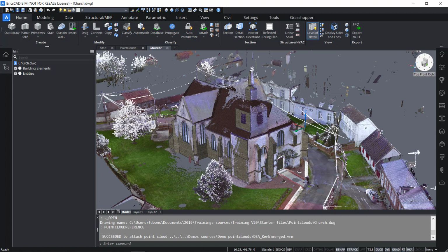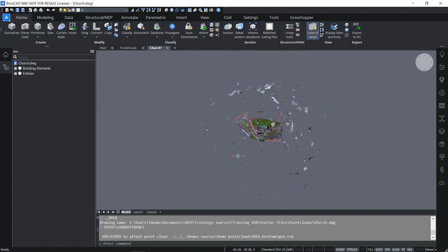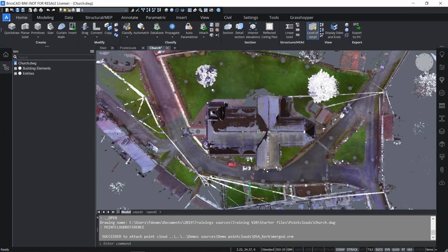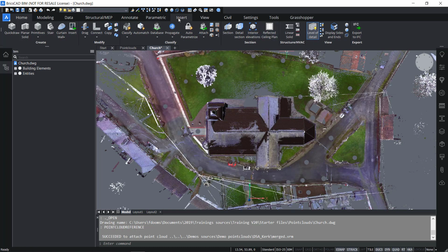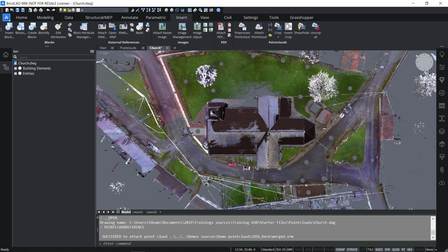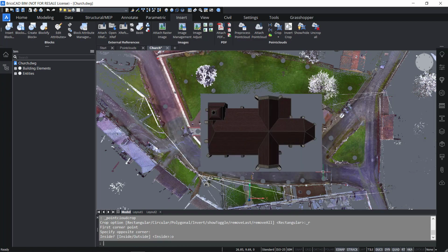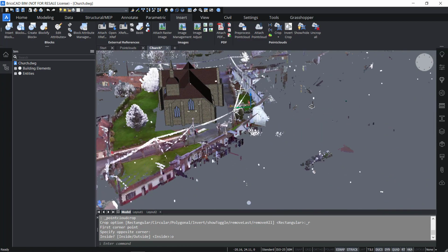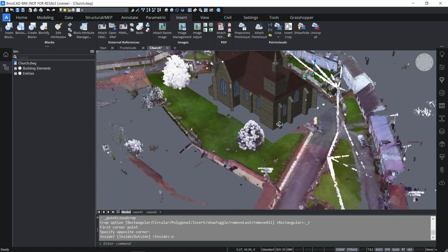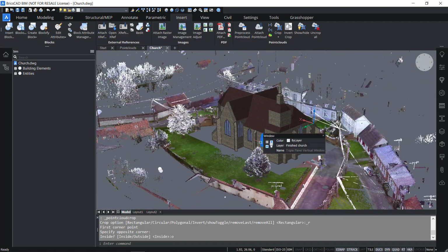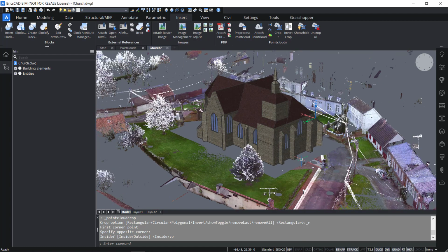I can show you the same things that I did on the pump before. So I will crop out the inside of where I modeled. I use the crop command and I draw a rectangle over the place where I made my model, and I choose outside to only show the outside, and then you can see the model church in its context, which is a pretty nice thing you can do with the crop command.